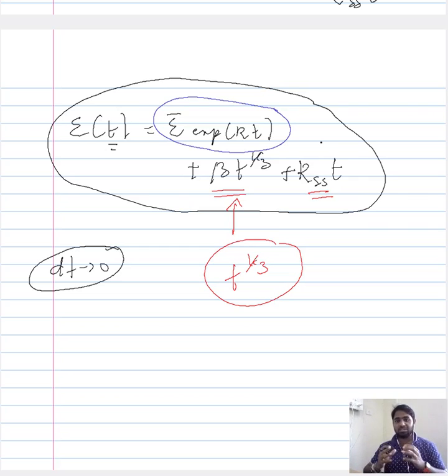Even though this does not have an explicit understanding of the different stages of creep, it is purely based on experimental observation, and all these terms were based on the best way to fit the data. This is a cumulative expression that helps us quantify how much strain a material would exhibit during a creep test. If you don't know in which stage it is, you can use this expression and calculate the overall strain of the material during the creep testing.